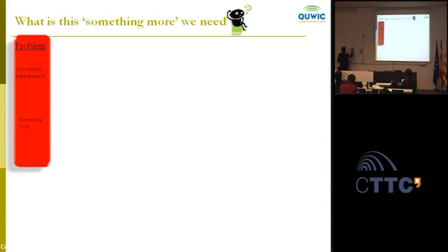I went to the site and saw that the base station RF antennas providing coverage were working fine, but the microwave link to another base station, which was actually the BSC, base station controller, was not working. I was unable to detect a transmission between the two. It was working till last night, but not anymore. So all of this very critical area was not being covered because people were not able to connect back to the BSC. With all your theoretical solutions, nobody thinks about this kind of problem.